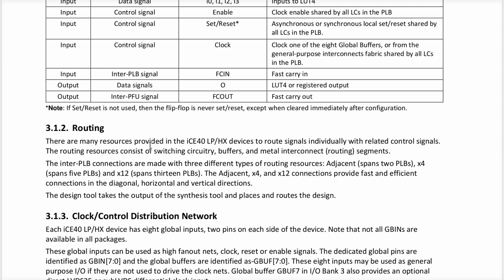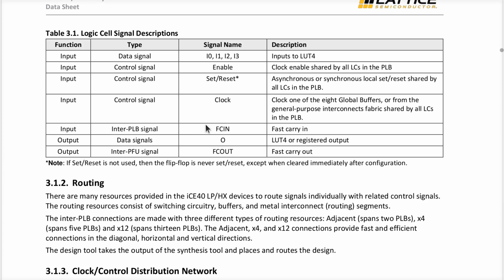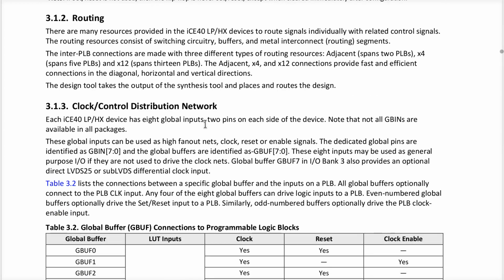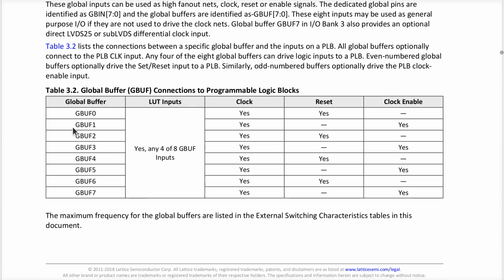And again, the tool knows how to deal with this stuff. The routing and the LUTs, that's the main thing the compiler can really do for you. But once you start dealing with, oh, I want a special routing pin or a signal that has to be globally routed throughout the entire chip because a whole lot of different things are going to use it, and I want to make sure there's a low latency path so everybody gets the same rising and falling edge at the same time.